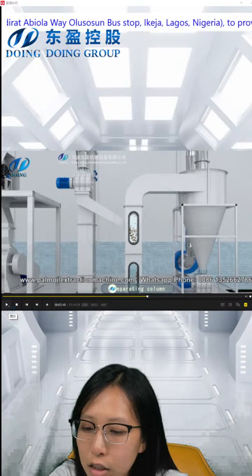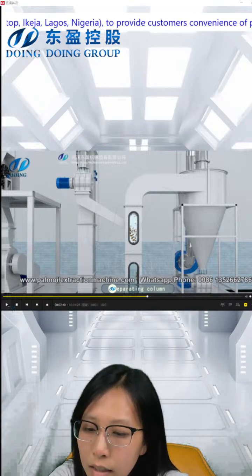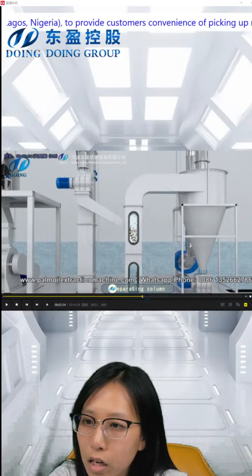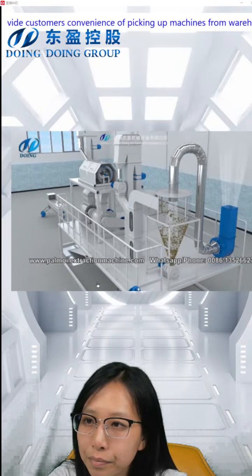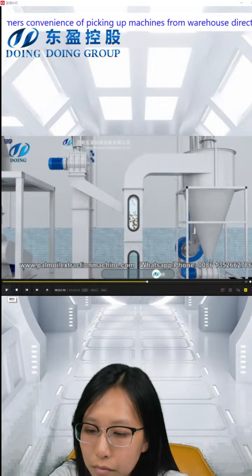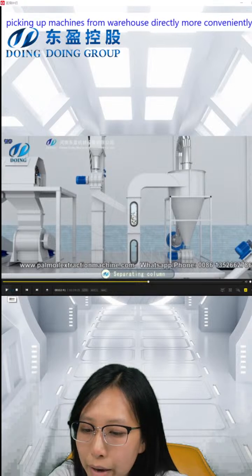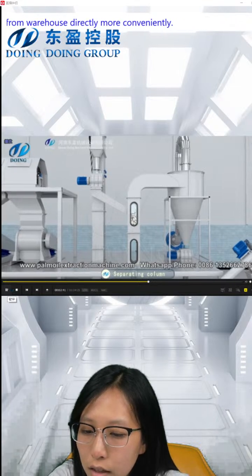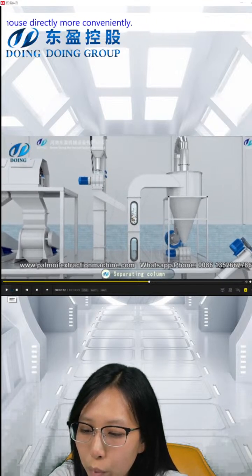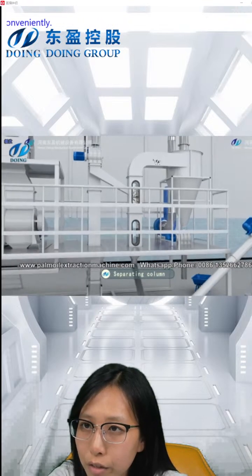According to the fan, under the centrifugal stage, the different specific gravity of kernel and shells is utilized to achieve the separation effect. The lower specific gravity, we see again, the higher, the lighter. The lower specific gravity shells enter into the cyclone through the wind, and the pipeline is connected to discharge from the workshop to ensure the working environment. The higher specific gravity kernel cannot be pumped away, and the wind separation column sends it into the kernel pressing stage.